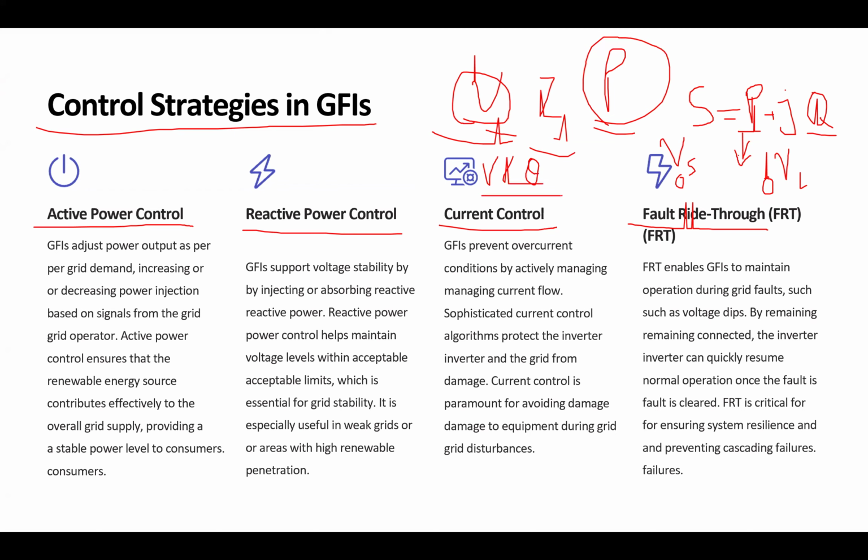Okay, this is a vector field. The active power is basically influenced by the phase of these two voltages. So if there is a difference in phase, that difference would indicate the amount of power that flows from source to load, or from point A to B, and that's it.